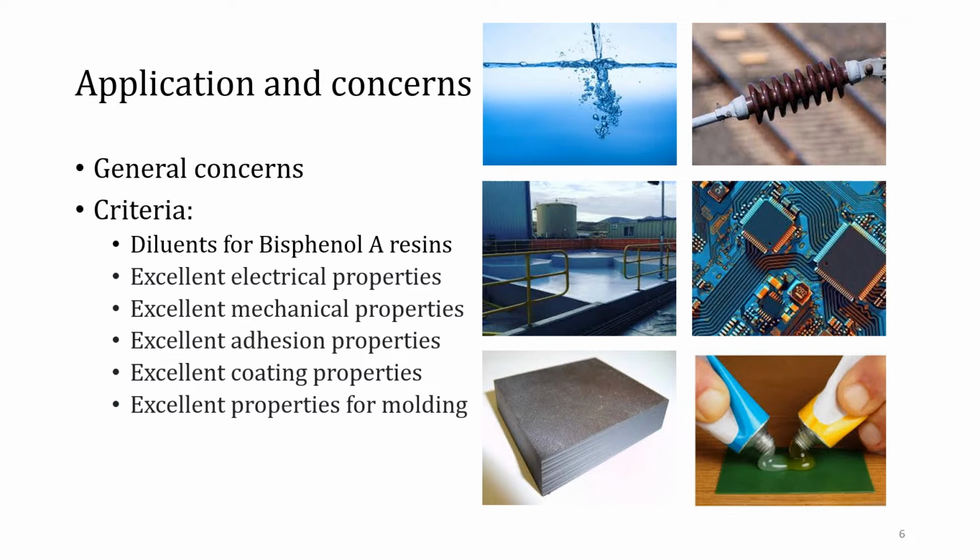An organic insulator made of cycloaliphatic epoxy resins can be used as an insulating potting material to replace ceramic products in outdoor high voltage devices. Compared with ceramic, it has the advantages of light weight, small volume, good impact resistance, and can be economically made into products of different sizes and shapes.